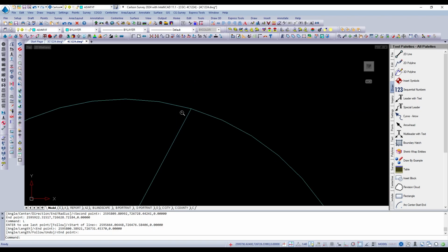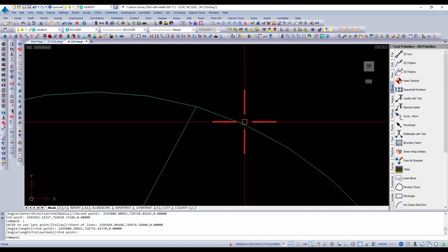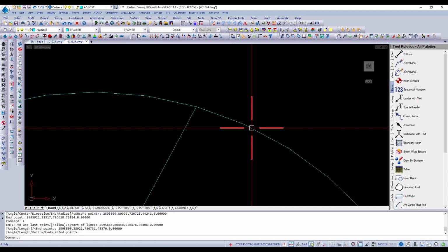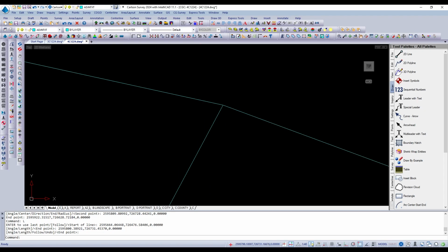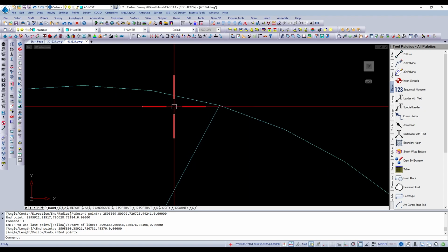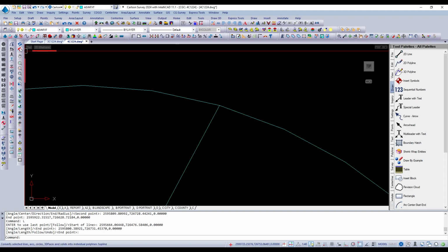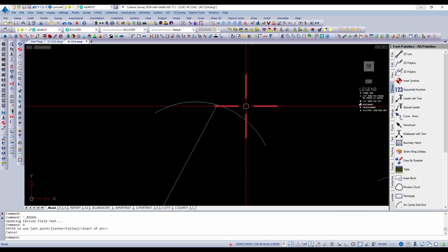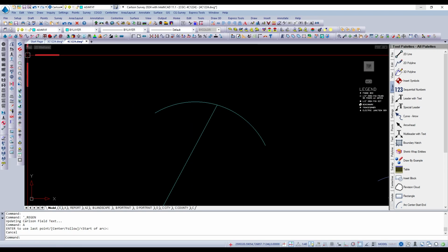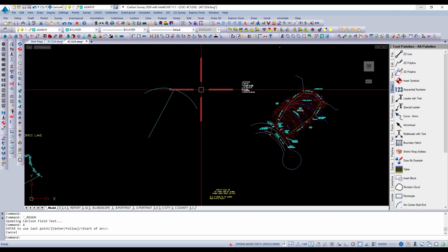Repeat what I did. So now you can see it's gone back to displaying as what looks like a series of straight lines. And the more I zoom in, now if I click regen, it smooths that arc back out. I like using regen because it regenerates all the entities and the coordinates for those entities. It's more effective than redraw. Redraw is just not that useful to me. I am always using regenerate when I want to regenerate my entities on my screen.